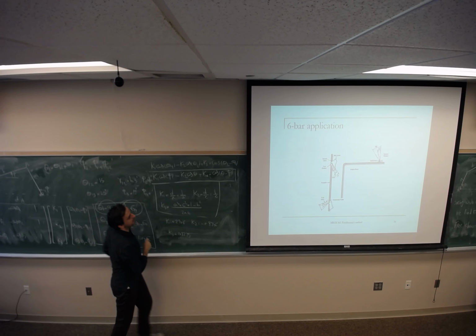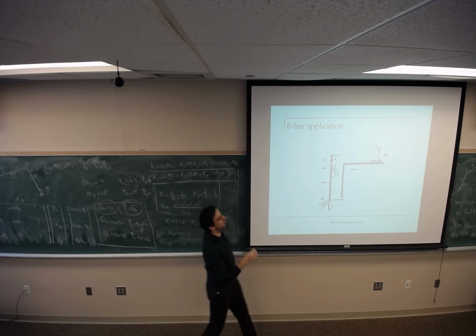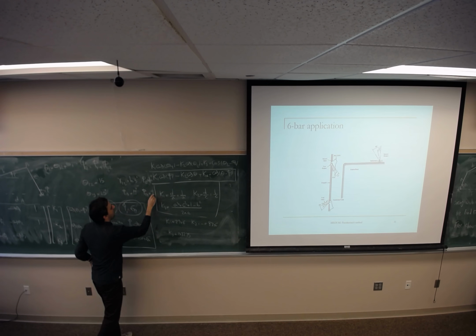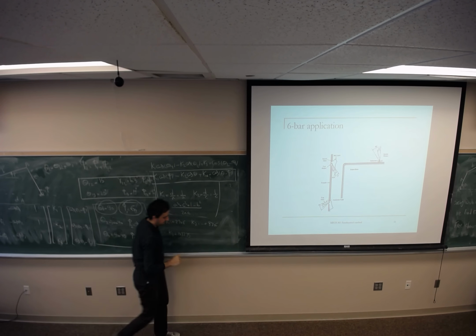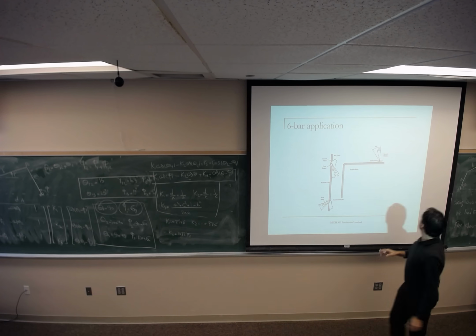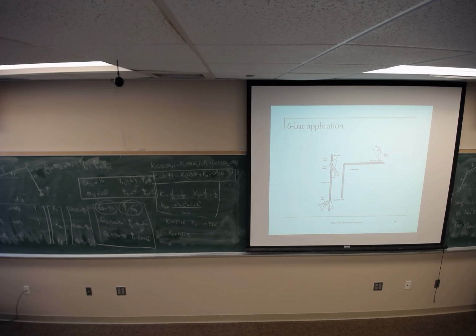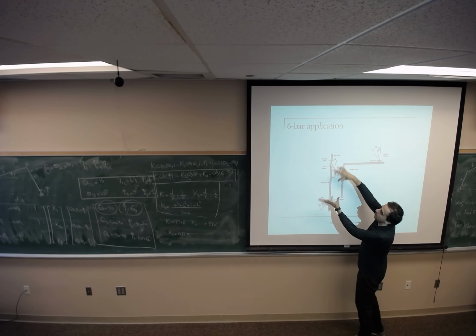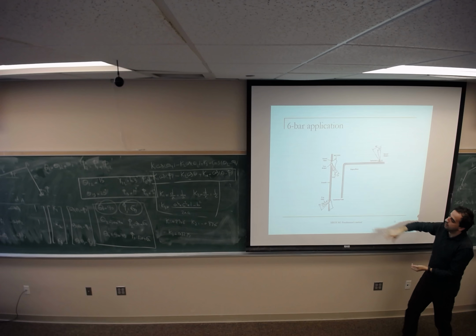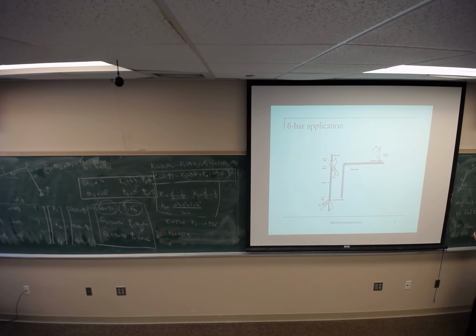And the carburetor should be open by 40 degrees. So this is exactly the same as this mechanism. We designed a 6-bar mechanism, a combination of two 4-bar mechanisms, which have been connected together through this terminal link.